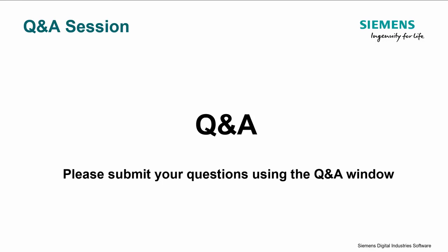Second question that's in, are there ways to create 3D PDF without having Solid Edge MBD? That's a great question. Also, the answer to that is yes. In the standard file save as, there is an option to save out as 3D PDF. And in actuality, if you have your PMI displayed at the time you do the save, the 3D PDF will also capture that information and save it out as well. That particular option has worked really well for a lot of our customers, and it's a great benefit.